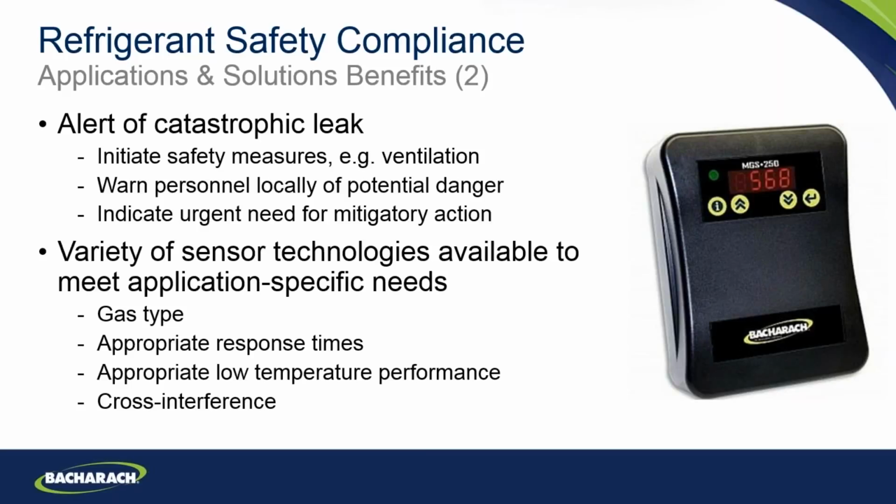The sensor technologies available to meet these requirements do vary by application, depending on the gas type, but things to look at in selecting an instrument include making sure that the instrument has appropriate response times and appropriate low temperature performance if it's going to be installed in a low temperature environment. It's also important to look at potential cross interference on the sensor from other gases that may be present in the application, and choose the appropriate sensor technology to try and avoid any issues that may arise from that.